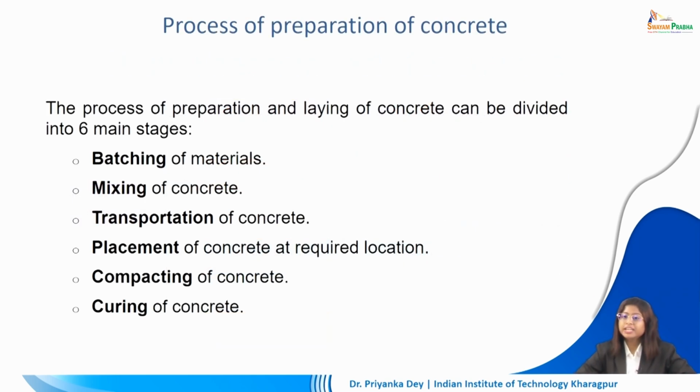When we are preparing and laying the concrete, it can be divided into 6 main stages: batching of materials, mixing of materials, transportation of the concrete from where it has been batched and mixed to where it is to be placed, placement of the concrete at different location, then compacting that concrete and finally curing that concrete.